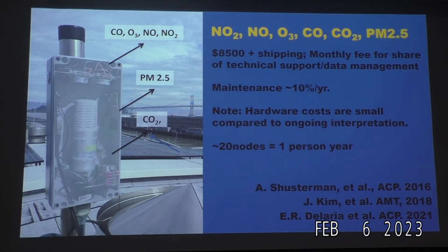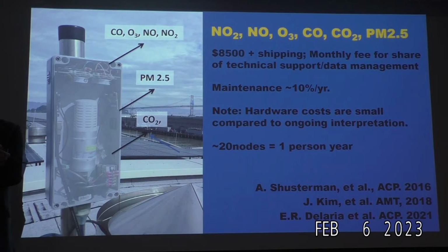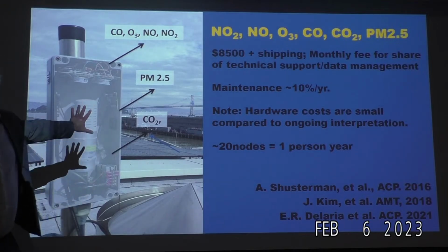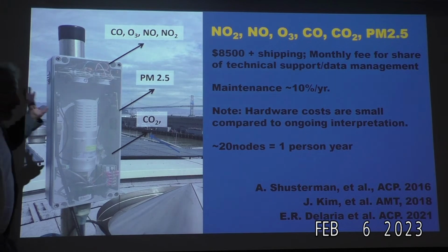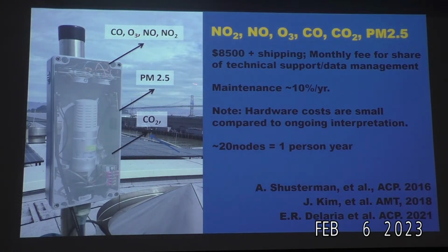So let me tell you what we're measuring. We're measuring CO2. That's the core of this. That's what drives the price. That's the hardest thing. To be interesting for CO2, you need to be measuring to about a part in 400. So it drives higher precision. The only other thing that we really usually care about in the atmosphere to that higher precision is temperature. 1 degree out of 300 Kelvin matters. But we don't care about the winds to a part in 400. We don't care about NO2 to a part in 400; for CO, 5 to 10% is good enough. For ozone, we care about a couple ppb out of 60. So really different tolerances. So CO2 is the hardest thing we do. And it drives the whole design of this project, really. But we measure CO, ozone, NO, NO2, and particles.